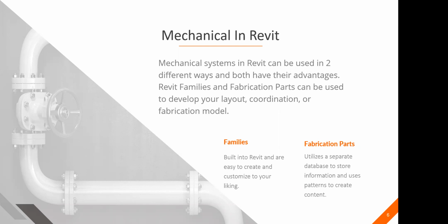And then there's fabrication parts. Fabrication parts are unique because their database is set in a separate software: CAD MEP, Fabrication CAD MEP, CAMduct, and I think CADmep. Those fabrication parts that you use with CAMduct on a CNC machine, those same fabricatable parts can then be inputted into Revit to create your system and service.